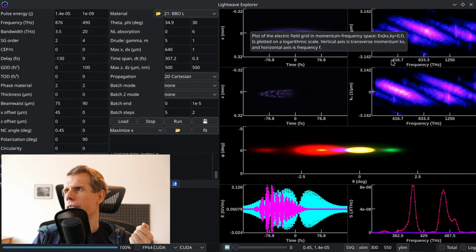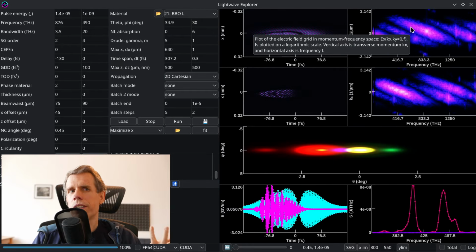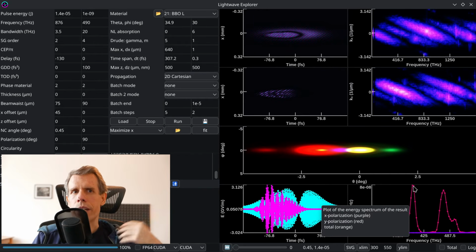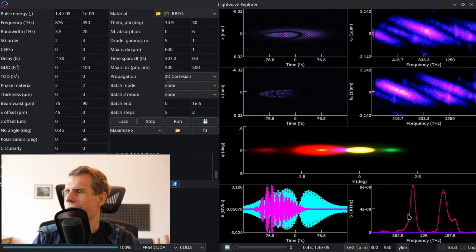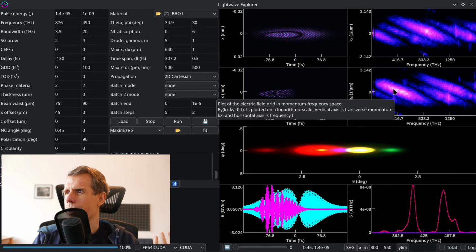All right, so now everything fits nicely inside of the box. Again, this is on a log scale, so if it goes to 0, it's really empty out there. You'll notice again that this spectrum didn't change when I changed that step size. So again, it's not too relevant for us because we know that these 2 spots correspond to these 2 spots, which are well within the center of the grid. But if we were really concerned about what some of these other parasitic processes were doing, we'd want to make sure that the grid is big enough to describe them.